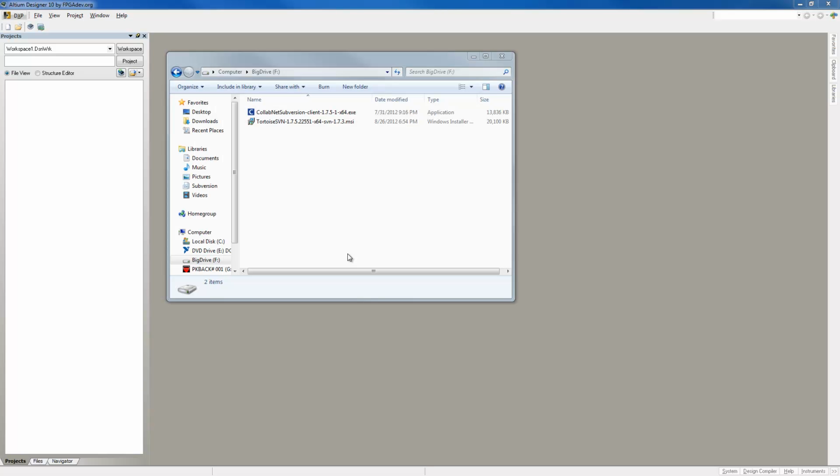All right, now there's two different ways to create a repo. One can certainly be done in Altium Designer. The other way is to use Tortoise, and I'll show both methods. Though keep in mind that normally, under most circumstances, you're going to create a repo and everybody in the group's going to use that one. So it's kind of one of these things that happens occasionally. It's not something that happens on a daily basis. It's the check-in and the check-out that normally happen on a daily basis, and we'll certainly go through that as we progress.